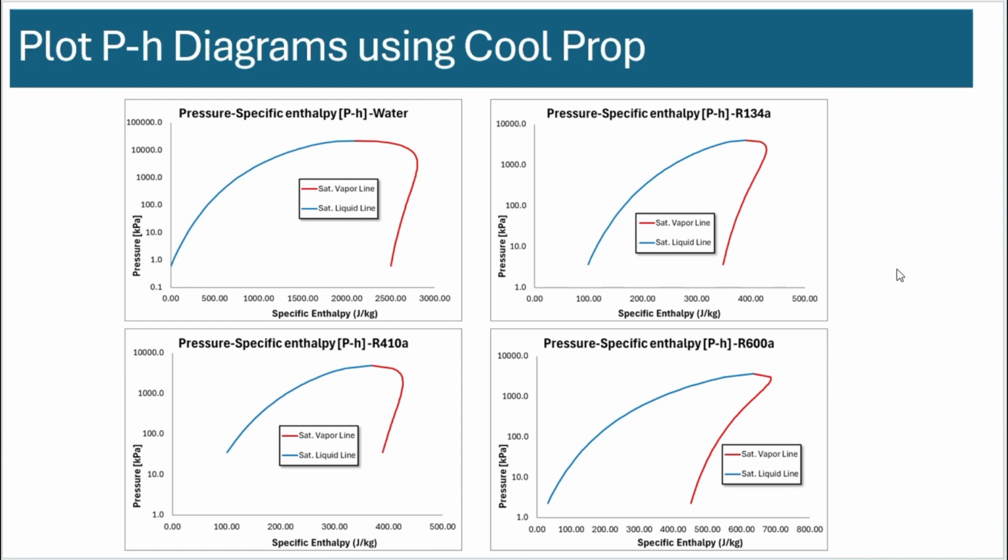And later on, you will see that the vapor compression cycle is typically denoted by something like this on this chart. Each of these process paths is part of some particular process in a vapor compression system. So this is basically compression, then condensation, then expansion, and then cooling in the evaporator.